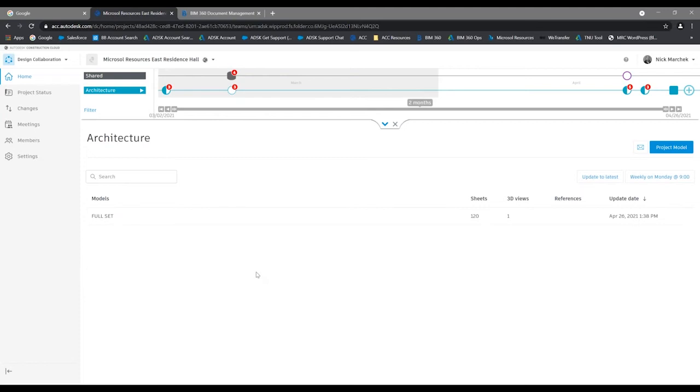That's a little more difficult than it is in the interface that I showed you a few minutes ago. So now with ABC Pro, I actually have access to that model coordination product, and I can run the clash detection on those models. Let's say, for example, my architectural model versus the structural model that I may have consumed from the package.